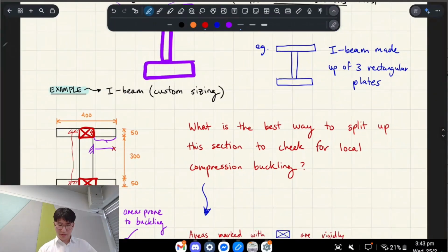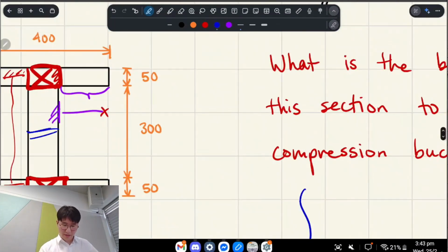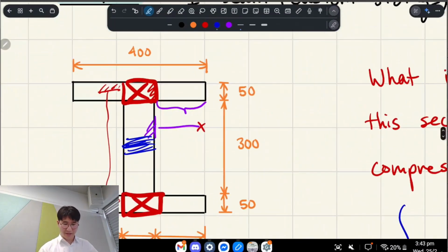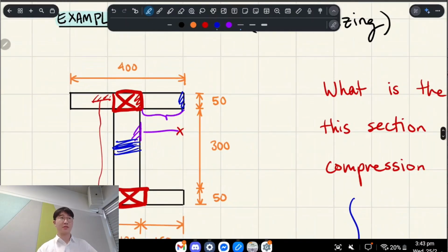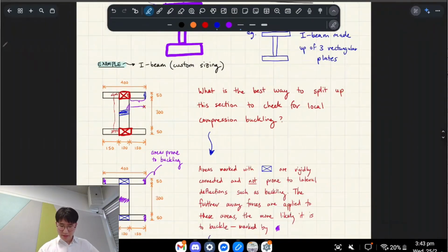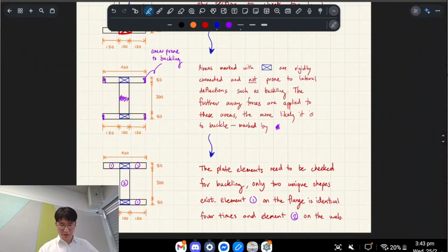So we know the weak spots are in the middle, because max deflection is going to be in the middle for a simply supported beam, or a beam that's rigidly supported on both sides. For a cantilever, it's the free end that deforms most. So here's the logic.